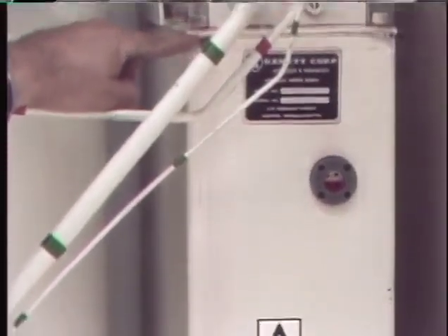Sometimes, while cleaning and inspecting an operating mechanism, you may find signs of a problem that needs further checking. For example, puddles of hydraulic fluid may indicate a leak in a hydraulic system. The source of the leak should be located and fixed.